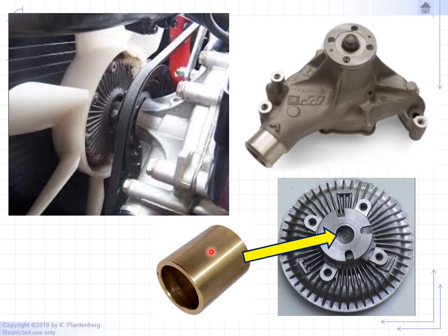You can, for example, tell them as long as the diameter is within 1.001 and 0.999 inches, then it's acceptable. So again, you mass produce parts, but you have to give the manufacturer some wiggle room as to how much they can be off by, and yet make it acceptable to replace an old part on the vehicle, for example. Next slide.